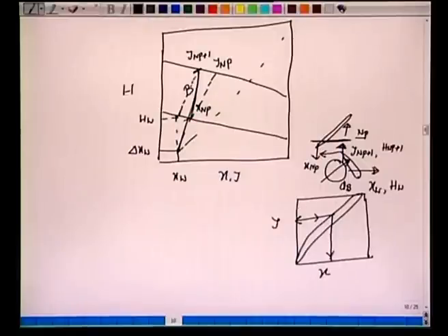Unlike in the previous case where we started from the top, knowing the vapor compositions, because in the top plate the vapor leaving was in equilibrium with this X1, so we had Y1 and X1. There we started from Y1 and got X1. Here in the stripping section we very often have to start from X and get Y.